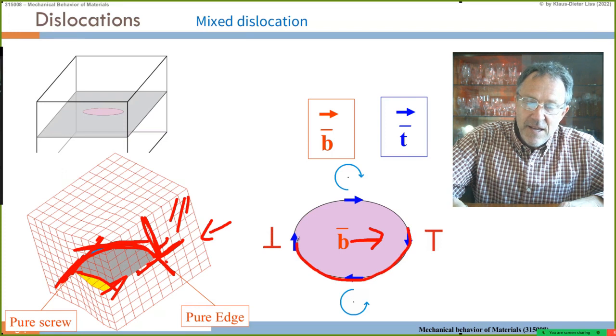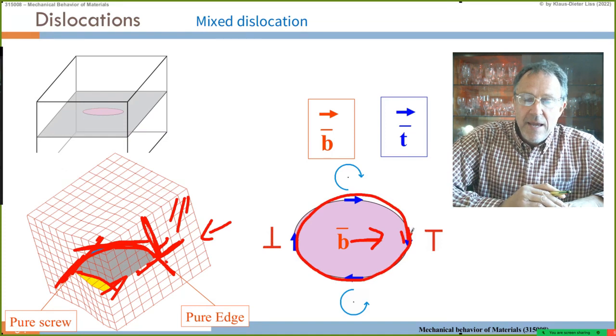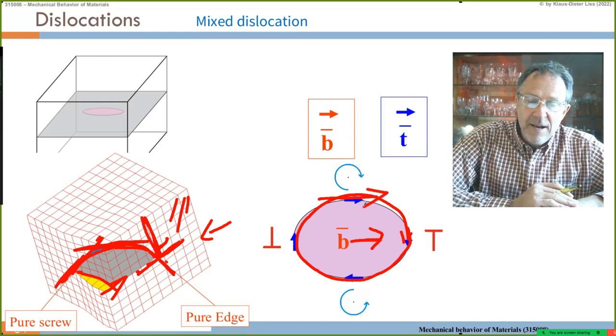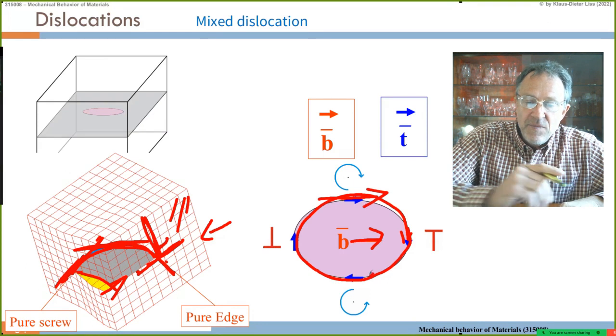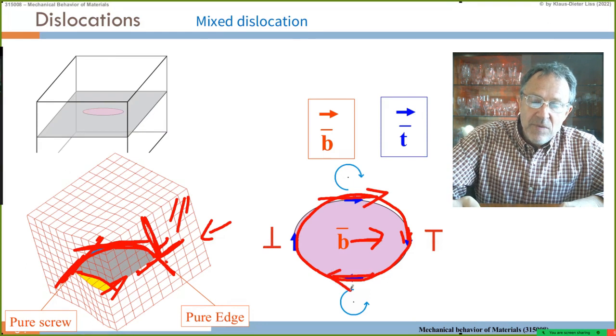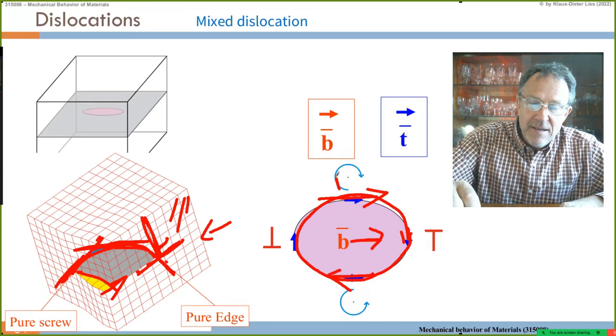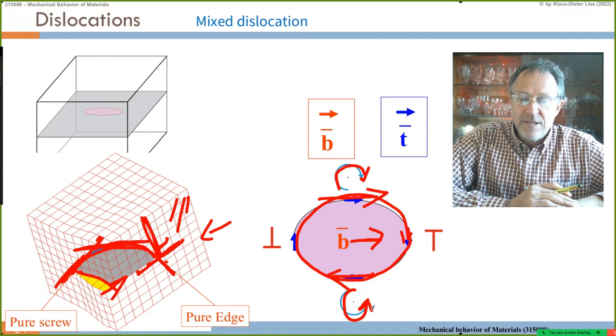The dislocation line goes in this loop where we have parts with the Burgers vector parallel to the dislocation line, so screw character, or anti-parallel, it's also screw character. The one we say it's a left-handed and this is a right-handed screw dislocation.